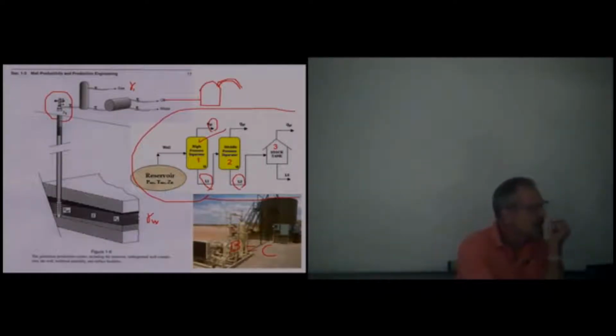Okay, so theoretically you can have a gas off your second stage separator, and you can call that gravity 2, and you could call that gravity 3. And then the oil that comes out of here doesn't have a gravity, it has an API, right? This is fun, I'm trying to write with the mouse. It has an API, and it's using degrees API.